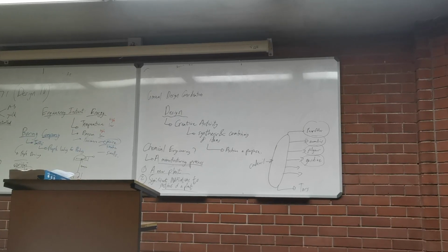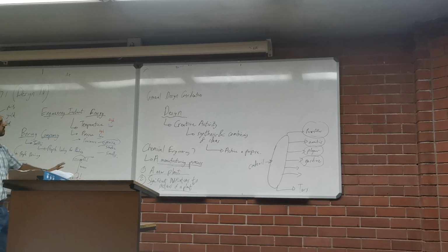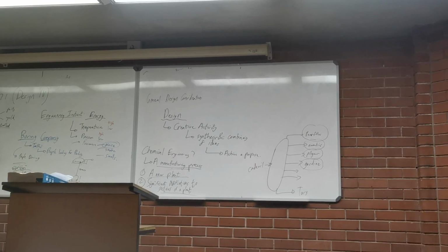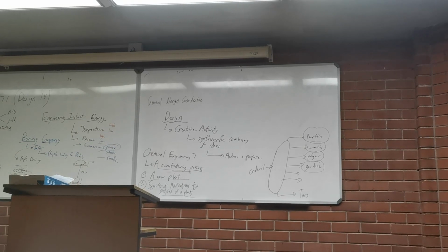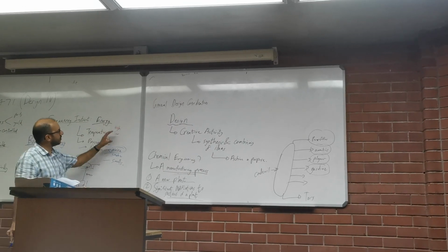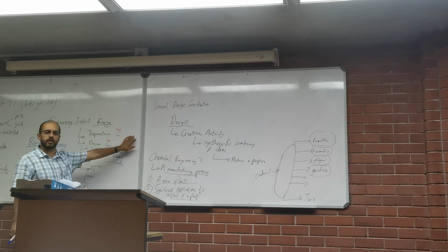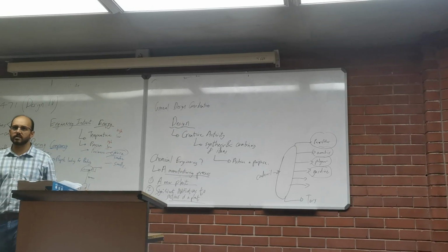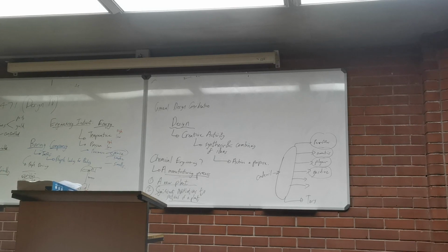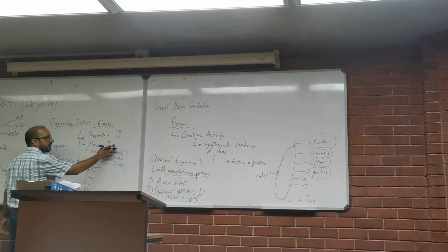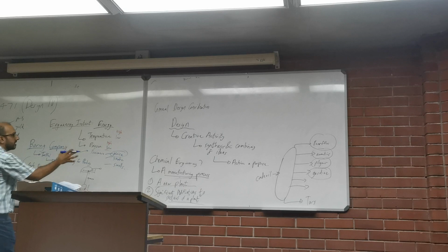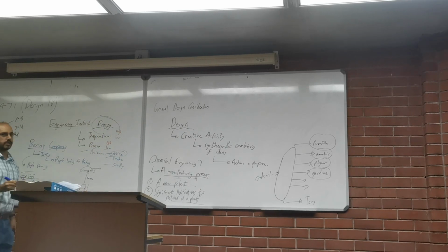Okay, now translate this instinct into your designs in terms of economic viability. Anything that's going to require high energy is going to ultimately cost a whole lot of money. It's ultimately going to be a trade-off. Maybe there is a certain catalyst that you can use to work at close to room temperature for your reactions, but maybe that catalyst is too expensive. Or maybe it's not so expensive, in which case you'll design your reactor accordingly. In certain cases, high pressure or low pressure, you have no other choice. So you need to weigh the options based on what is going to save energy.